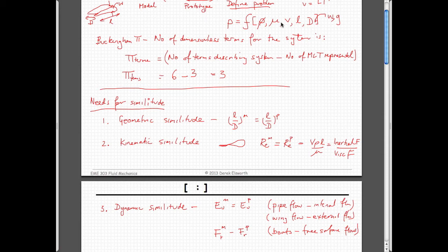Because it's the weight of the air. But the dynamic forces applied on the wing by the velocity going past it, providing lift, are probably 3 orders, 5 orders of magnitude larger than that pressure. So I guess what it's saying is that the pressure difference across the wing due to gravity is much smaller than the lift that you get from the velocities around it, and therefore it just doesn't make any difference.